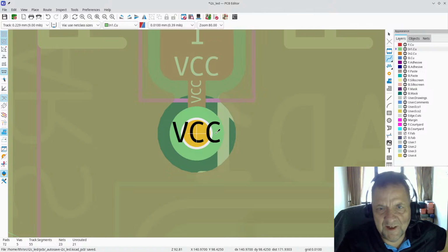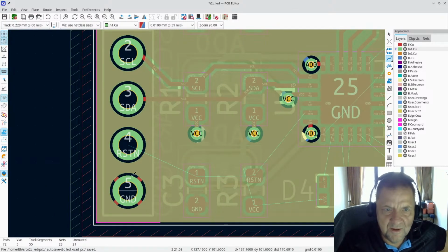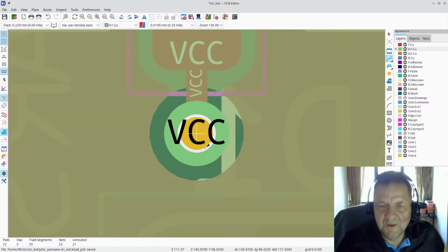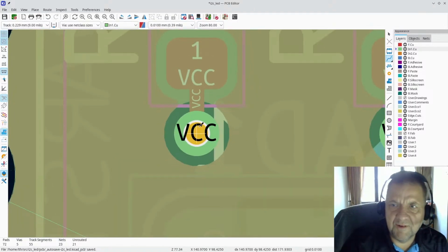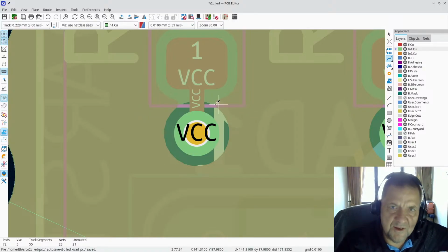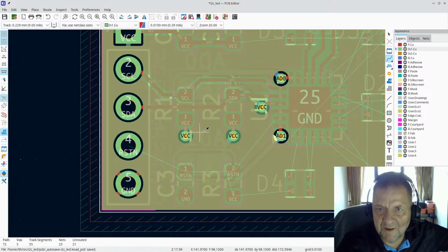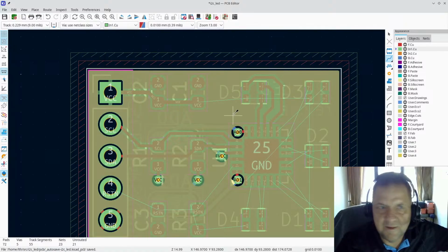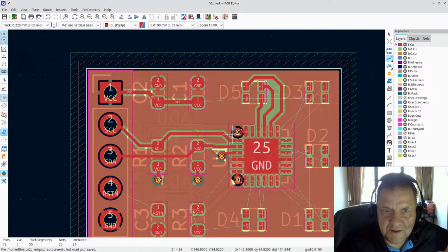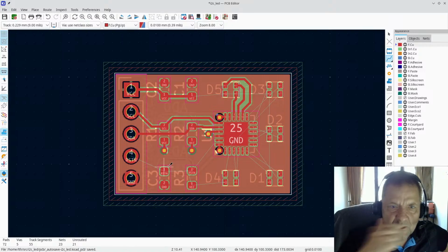It is not spaced. It doesn't look connected, but it is. You can see over here it gets black if it's not connected at all. So it is connected to the ground layer and VCC and none of the other layers. You'll just have a spacing around it. And that is about it. I think that answered the via question. Let's go back to our routing.